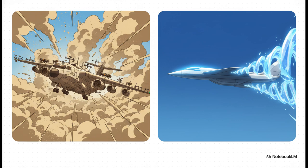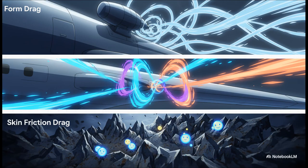It's a package deal. Okay, the crucial thing to remember here is that parasite drag actually breaks down into 3 specific subtypes. First, form drag. This is all about your aircraft's shape. Think bulky engine cowlings or antennas. Second is interference drag. This happens when airflow from 2 different surfaces collides. Like right where your wing meets the fuselage at a 90-degree angle, it creates these swirling, turbulent eddy currents.